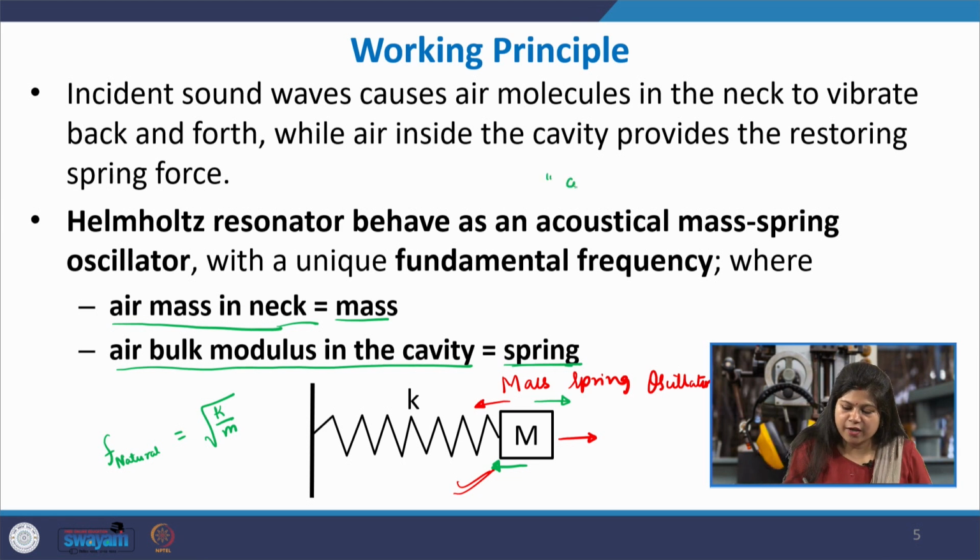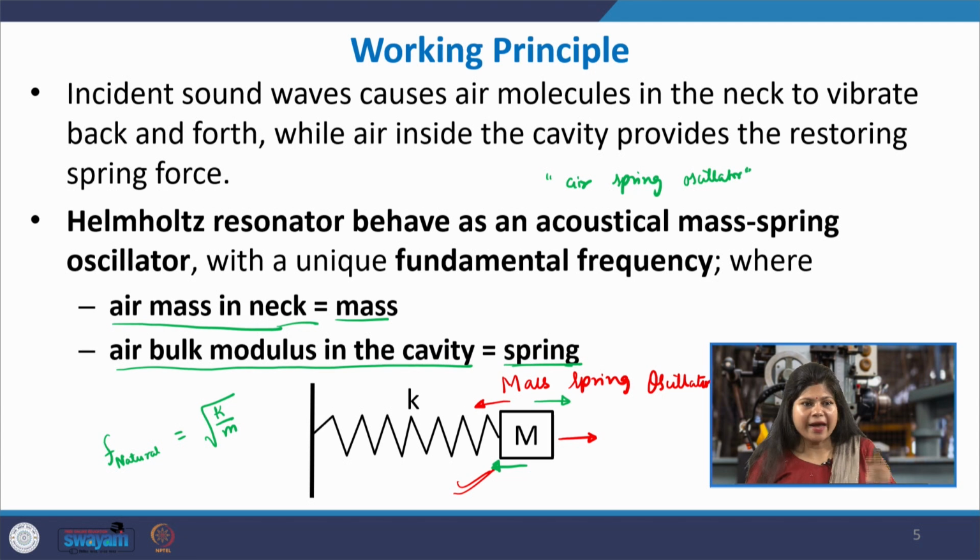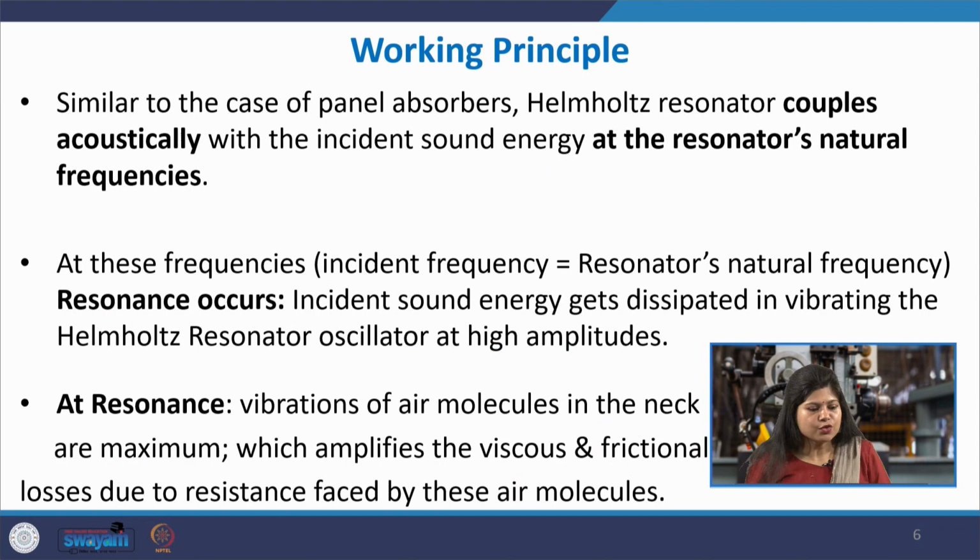So, it is also called an air spring oscillator, because here the confined air is acting as the spring element. Suppose you have an incident sound wave at the same frequency as the fundamental frequency of this resonator, then there will be something called acoustical coupling.